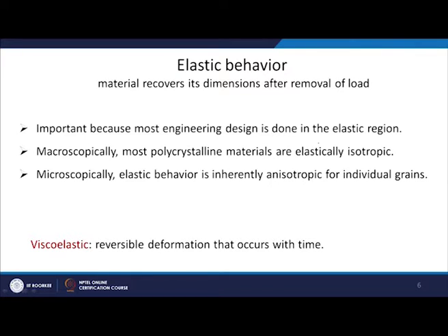Then there is another concept called viscoelastic properties of material, in which case the reversible deformation that occurs is dependent on time. If it is not viscoelastic, normal elastic behavior, then as soon as I leave the load, it will go back to its original position without any time delay.